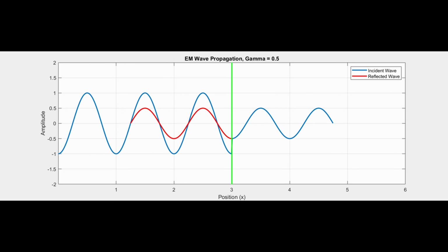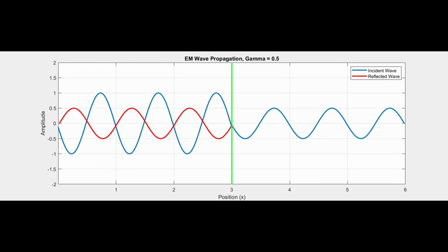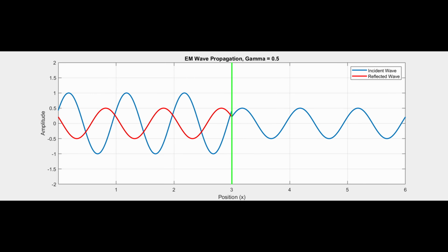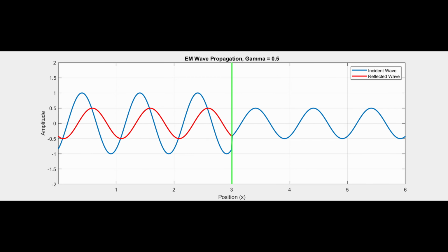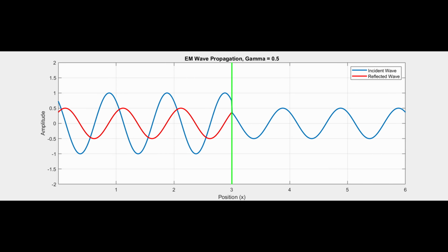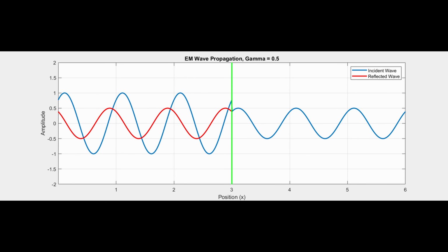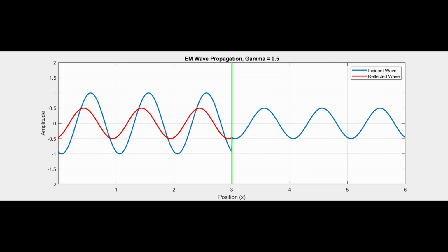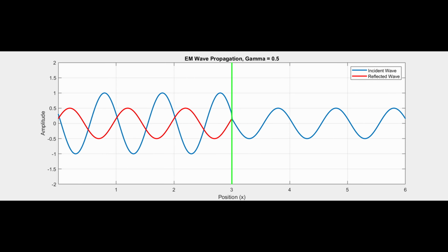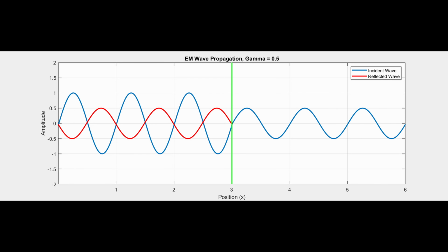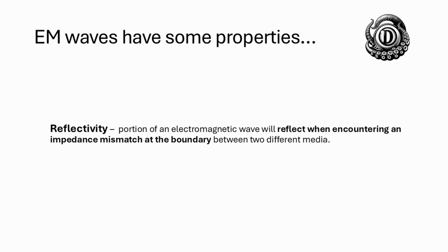Now imagine this wave traveling through a coaxial cable and hitting a boundary at port 1 of a network. For example, an antenna, software-defined radio, spectrum analyzer, vector network analyzer, VNA, whatever. We're interested in knowing how much voltage passes through port 1 into our device, whatever it may be. If the characteristic impedance of our coax matches our device, most of the energy passes through. To quantify this, we measure S11 using a VNA.